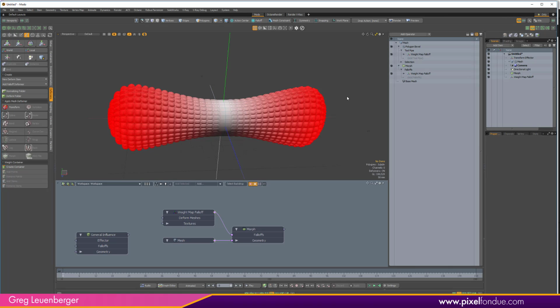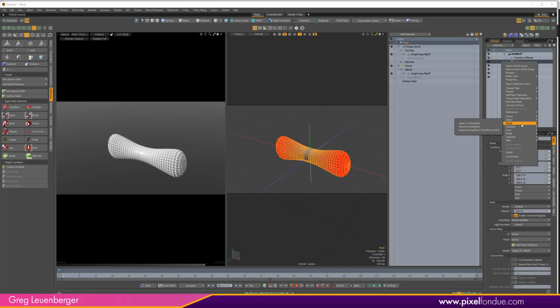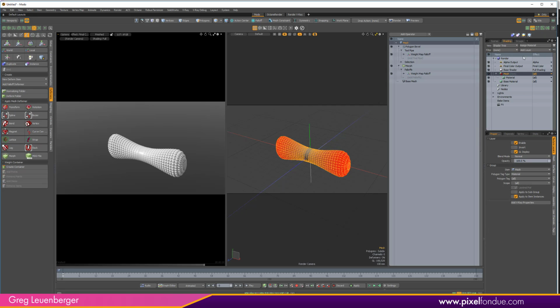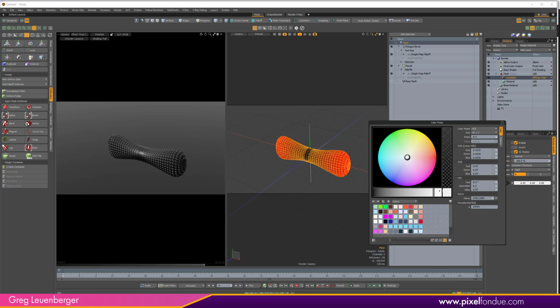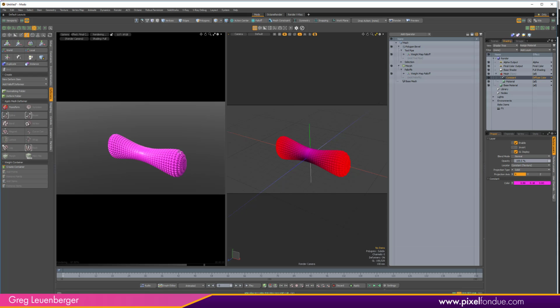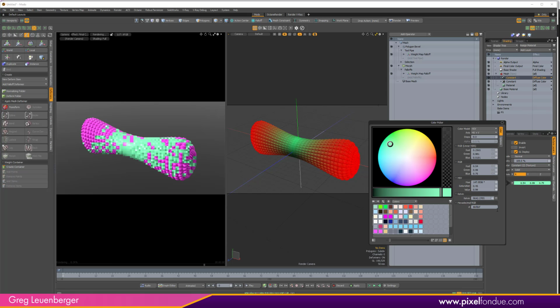And you can even use them for texturing. So we can do a couple of things. I didn't create a mask for this guy, so let me just create an item mask. So shade and create item mask, and then we've got an item mask. And I'll just do a processing constant, and we'll make this a color like, I don't know, about that color, sort of that purpley color. And great, so we can do a couple of things here. Let me just duplicate this constant, and I'll make this one a complementary color there.